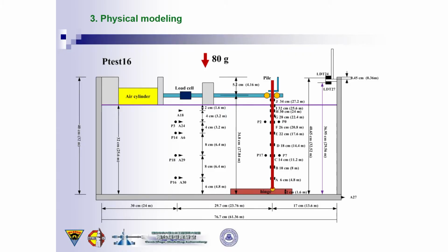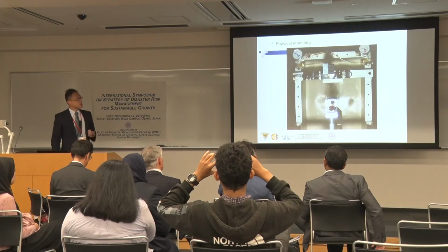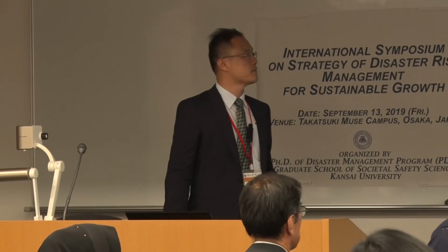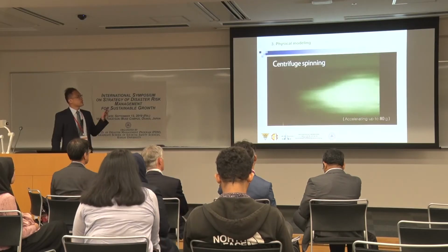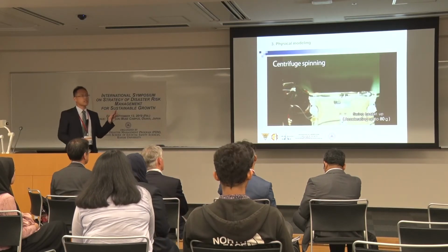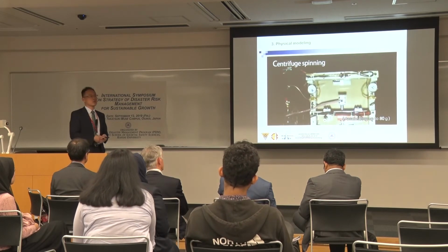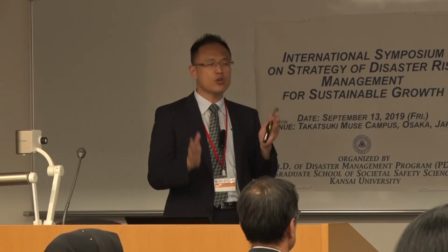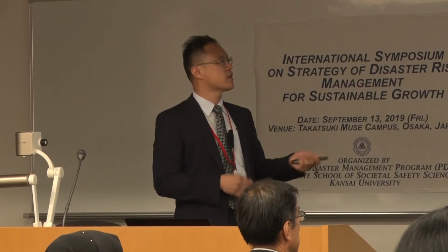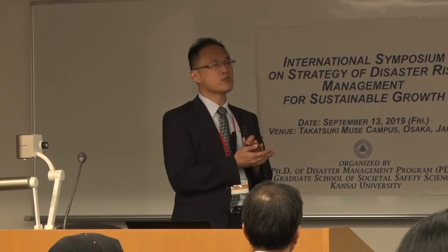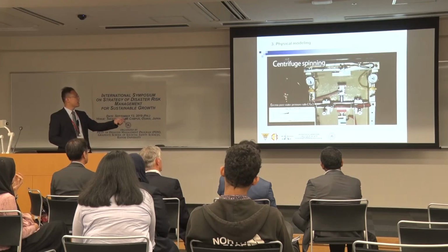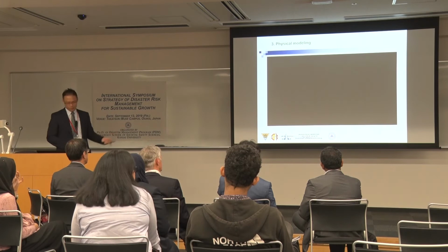And then this simulates the normal pile foundation. During flight, we can apply the load to get the PY curve of the monopile foundation for wind turbines. This is especially relevant in Taiwan, because we would like to develop wind turbine energy, but the soil around Taiwan is liquefiable. So in this test we input the base shaking and we would like to know the PY relationship during soil liquefaction. Okay, it has already liquefied, and now we push.